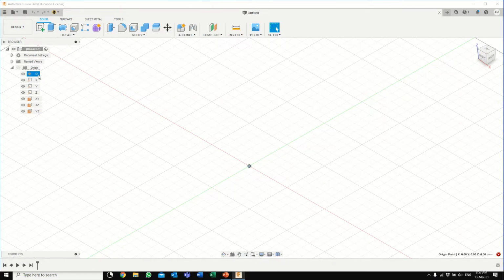So if you click on it, this is the origin. It will show directly the x-axis, the y-axis, and the z-axis. It's important to note how the axes are oriented by default, because in some software these axes are changed by default. So if you draw here vertically, for example, in Inventor it will be horizontal because the z-axis is in this direction.